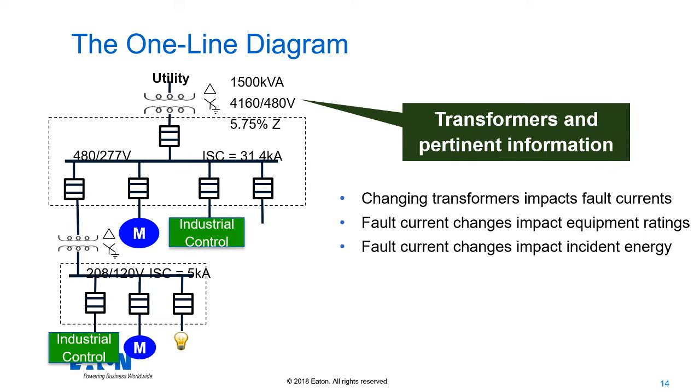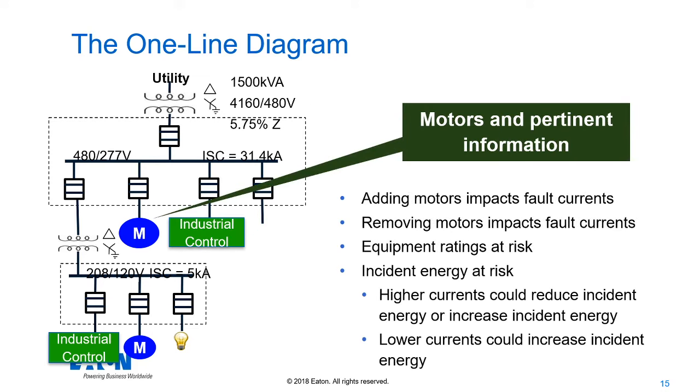So other big components in a power system are your motors. Your motor information is really important, because that's going to be another fault contribution. It's going to possibly contribute fault current. It could also contribute to harmonic content, depending upon whether those motors have variable frequency drives. Somehow you should indicate whether or not there are VFDs there, because that is another very critical part of the picture. That's a detail that's important to understand the harmonic content and whether or not you'll have fault current contribution. So adding the motor, you'll usually have the horsepower of the motor there.